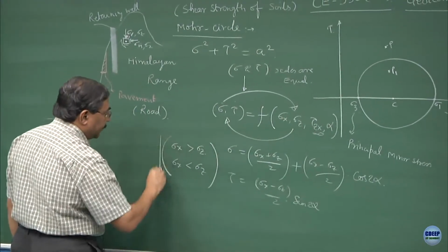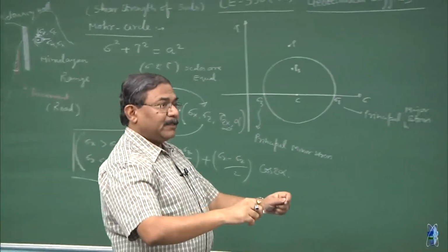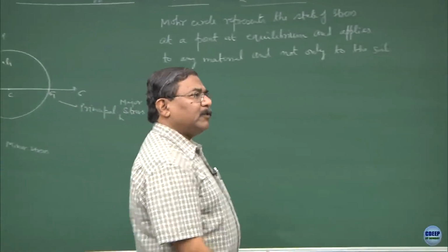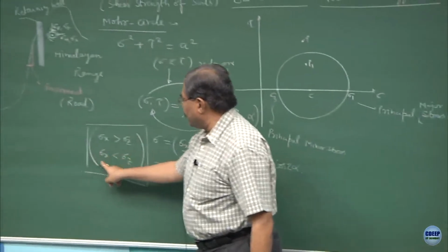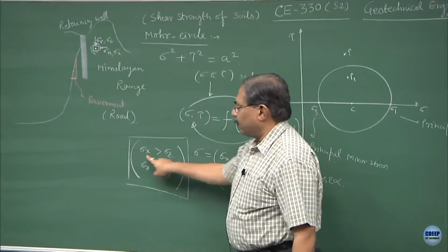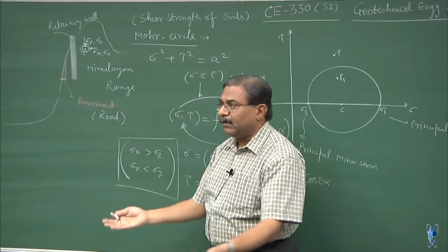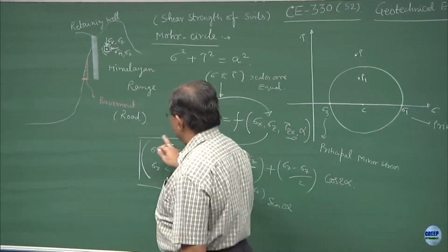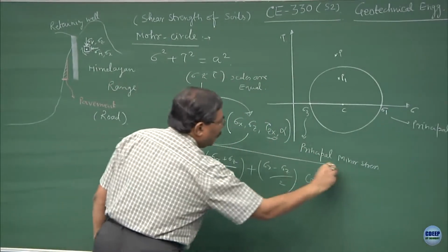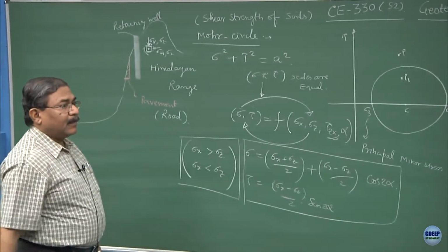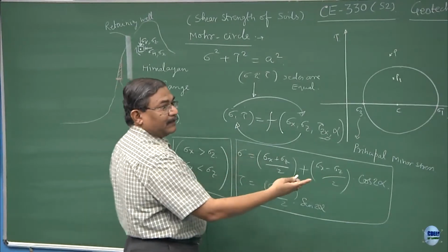If I can project and solve the state of stress which exists in geomaterials for different real life situations, clear. So, this is a typical case of, let us say, tectonic motion, formation of a hillock, plates coming and hitting each other, lateral stresses more than the vertical stresses. This is a reverse situation. So, I can still use these equations. What I will have to do is just substitute the values of sigma x and sigma z with sigma 1 and sigma 3.